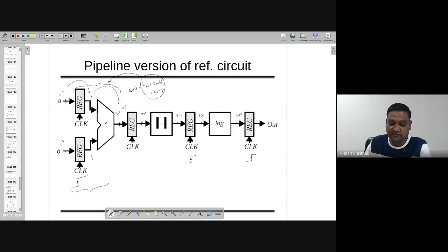If you are using a sense amplifier based register or something like that, then this value will be VDD, because when there is a clock, it's VDD, or it will latch the previous value. Right now there is no other previous value available, so I may reset it, or maybe I can recharge it, right? Any one of those things I can do.